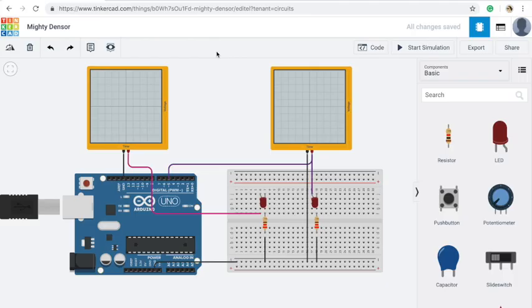I wanted to compare basic switching on and off of an Arduino pin without PWM versus using a hardware PWM pin. For this, I made a simple LED circuit with an oscilloscope. The first LED with our software PWM is connected to pin 8 and the second one with hardware PWM is connected to pin 5. Of course, there are some advantages and disadvantages for both approaches.